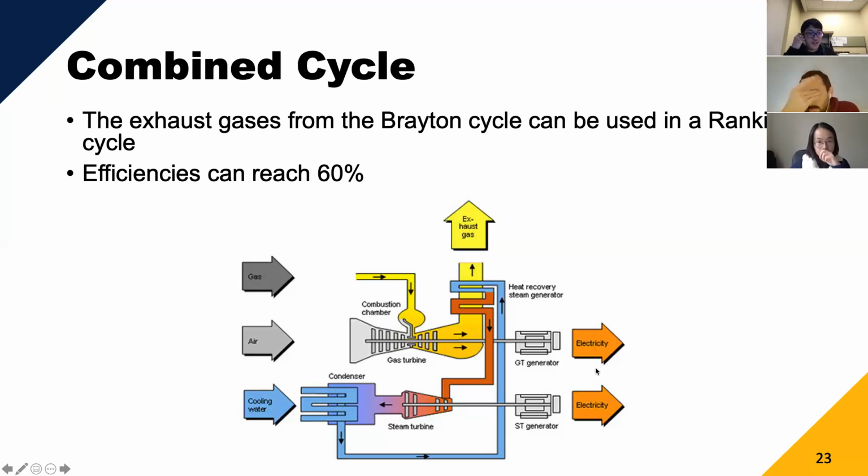You can essentially start the turbine spinning and combust your natural gas and extract energy to power your generator very, very quickly. Whereas within a steam turbine, you have to spend some time to heat up and boil the water, get it up to its ideal operating state.